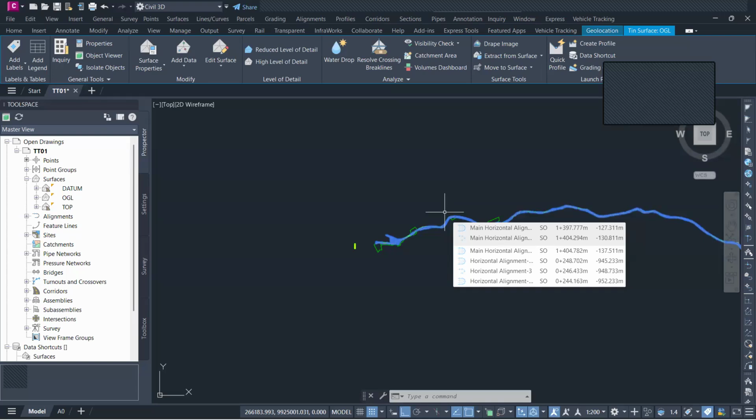Now, there is another item that is called site clearance. Site clearance is always paid in square meters. And this is mostly a unit rate that is given as a standard rate. And I'm going to also show you some manuals that we use for cost estimation here in Kenya. But again, it is the area. So how do you calculate the area in site clearance?